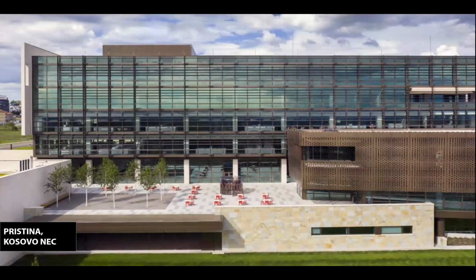They are for both. The main challenge for retrofit is a lot of people think you can put ballistic rated glass into an existing frame. Two reasons you cannot. One, the glass is essentially going to be too thick for the glass pocket on existing storefront that was not security rated. Even if you were able to, the frames are not rated to stop bullets or bombs or blast or storm impact threats or forced entry. So that's essentially the challenge with retrofit. But yes, you can utilize our systems if you were to pull out the entire system, for retrofit application and new construction. Fantastic question.